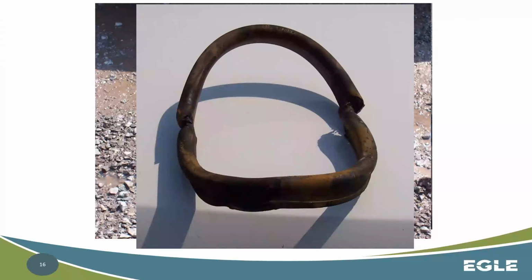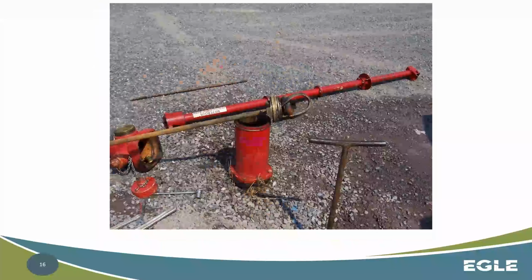So, you have to understand your operations of these hydrants. I'm pretty sure you had a moment with components where they talked about how hydrants are. I'll back up just a minute to just refresh you. If you look at this, the hydrants close against pressure. So as long as you don't have an obstruction like this, you should be able to mainly and mostly close down a hydrant.